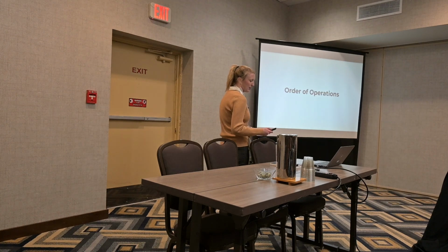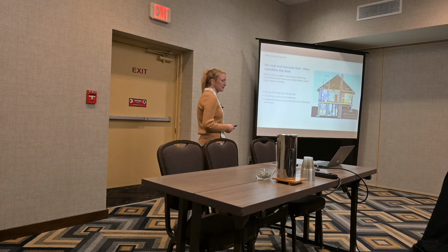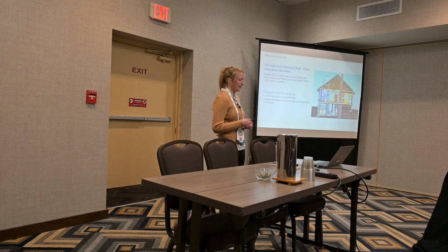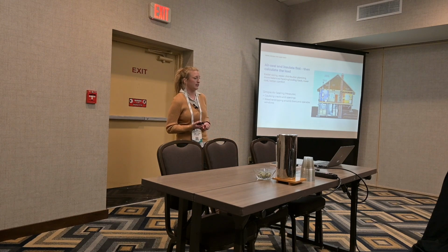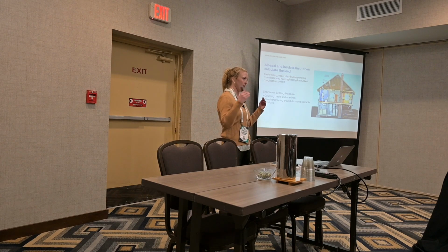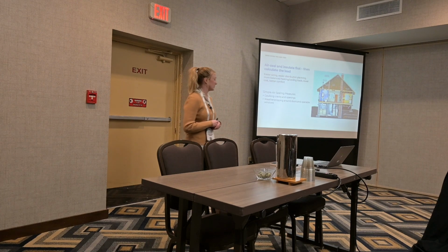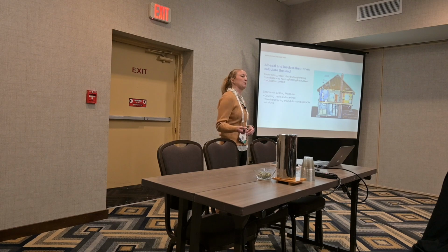So let's talk about the proper order of operations. First, before sizing and installing a heat pump, it's always best to upgrade the home by air sealing and insulating first. And then after you've reduced the load is when you can perform the load calculation and install a heat pump.